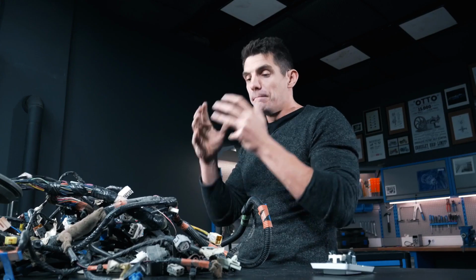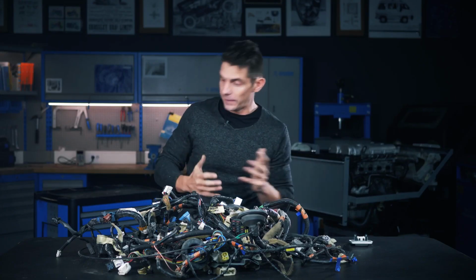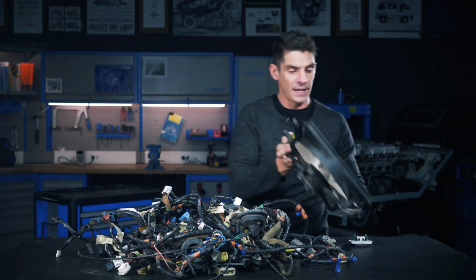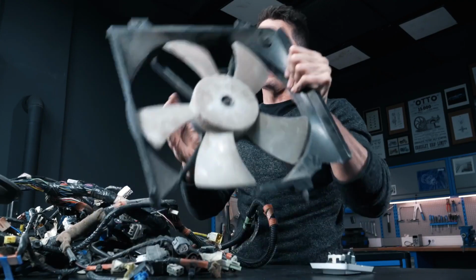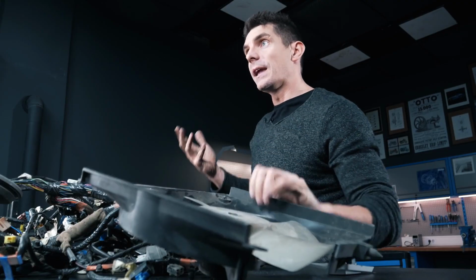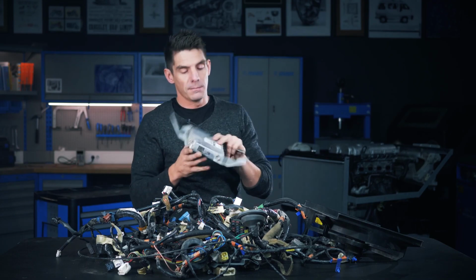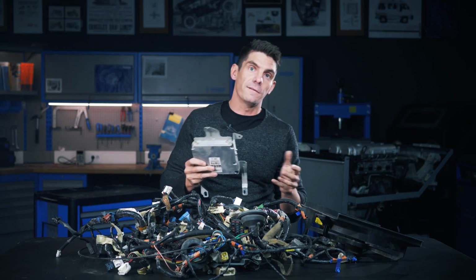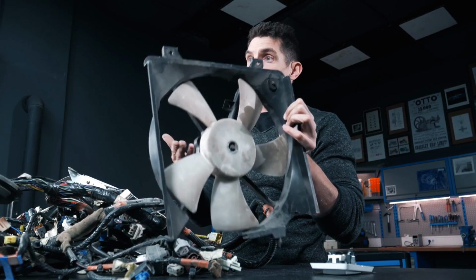But these days, most things, maybe, are controlled electronically by microchips and engine computers. The cooling fan is an example. Here's a cooling fan from this engine. Now the cooling fan is controlled by the ECU. The cooling fan is electrical and the ECU is electronic. The ECU, here's the ECU, monitors the coolant temperature. So it looks at the coolant temperature sensor, reads the value of the temperature of the coolant and turns the cooling fan on and off as it's needed.